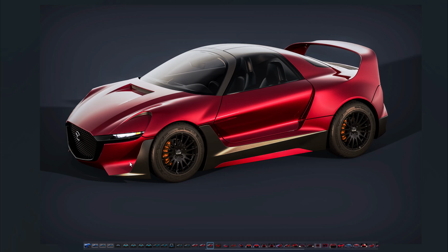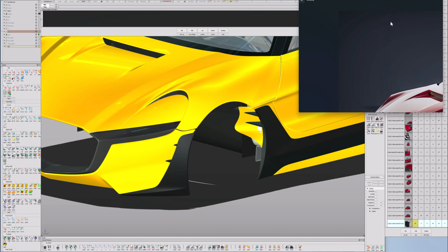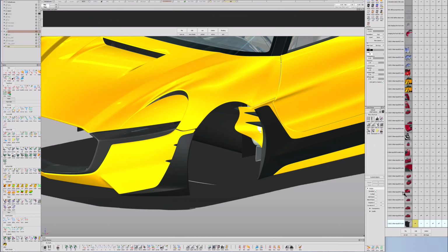Put the radius at 1, but the intensity at a few thousand, like 3000, and it creates super nice highlights and really rich, juicy highlights on the simple wheels and the car paint. Look how many small dots here. You can see how these shiny wheels look now. I really like it. Okay, let's go to the next points.